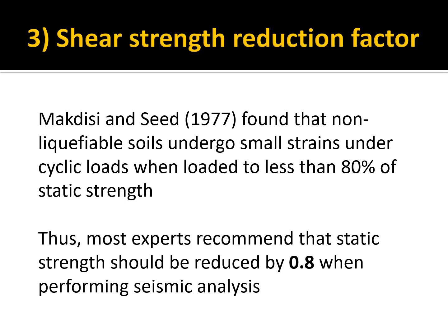And so we basically reduce our undrained strengths when we do our limit equilibrium analysis. So you've added the seismic coefficient K. That modifies the formula for the factor of safety, but you also use a reduced shear strength.